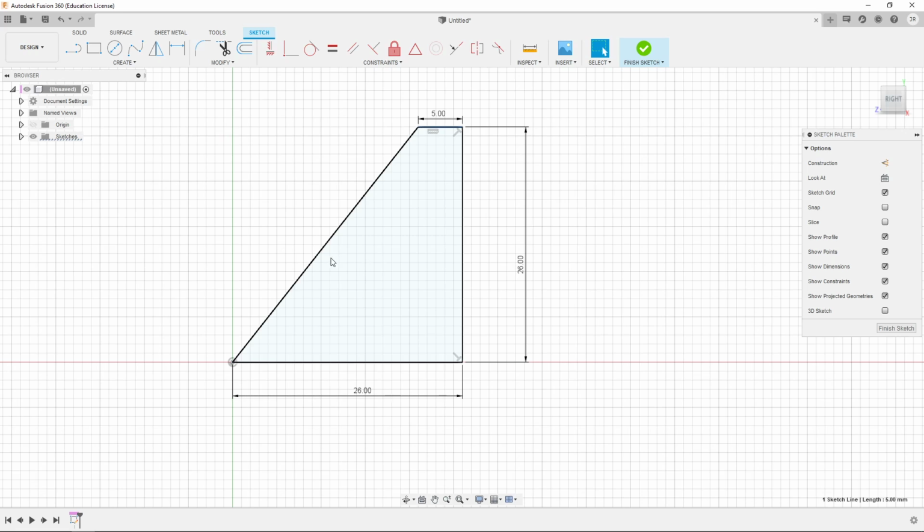horizontal, and by implication, this line has some length, and I don't know what it is, but I don't have to, right? The fact that I have these two dimensions and this height automatically lets the computer calculate this length. If I'm curious as to what it is, I could potentially use some tools to see it, but at this point, I am not interested. It's unnecessary to know. And it wouldn't even allow me to choose a dimension because it would say it would be over-constrained. The information is hidden behind the scenes, and it doesn't need us to help calculate it.